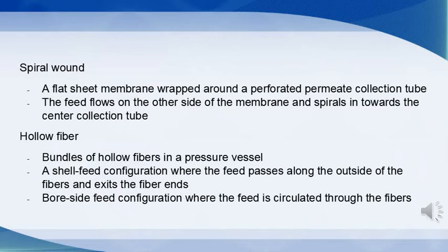Feed travels through the flow channel tangentially across the length of the element. Filtrate smaller than the molecular weight cut off will then pass across the membrane surface into the permeate spacer, where it is carried down the permeate spacer toward the permeate tube. The remainder of the feed then becomes concentrated at the end of the element body.